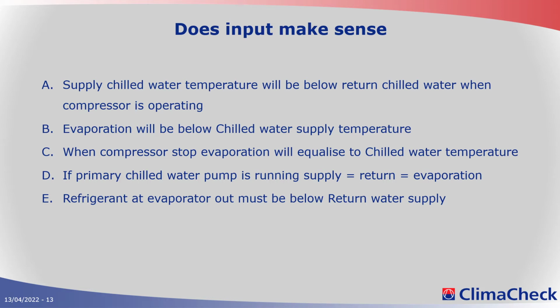So there is also a lot of this, if it makes sense. I cannot have a colder chilled water going out than the evaporation. So the evaporation always has to be the coldest temperature. These are just to bear in mind so that we know where the system should be.